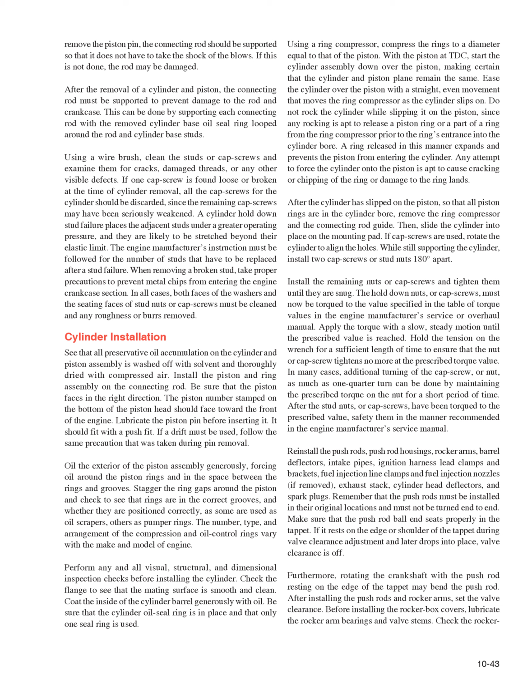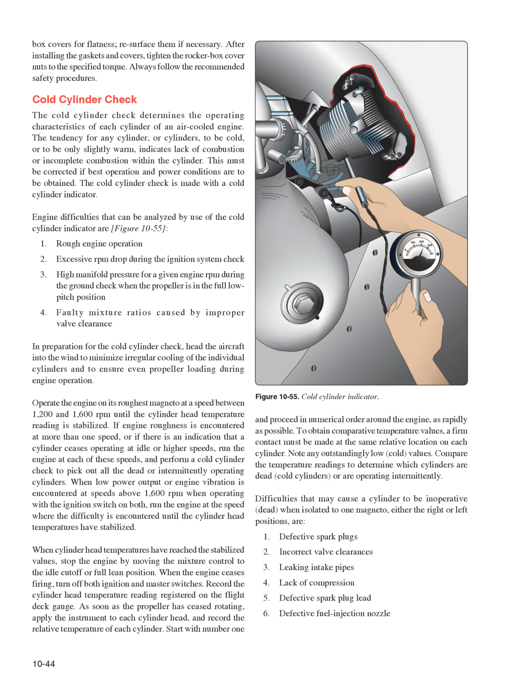Before installing the rocker box covers, lubricate the rocker arm bearings and valve stems. Check the rocker box covers for flatness, resurface them if necessary. After installing the gaskets and covers, tighten the rocker box cover nuts to the specified torque. Always follow the recommended safety procedures.